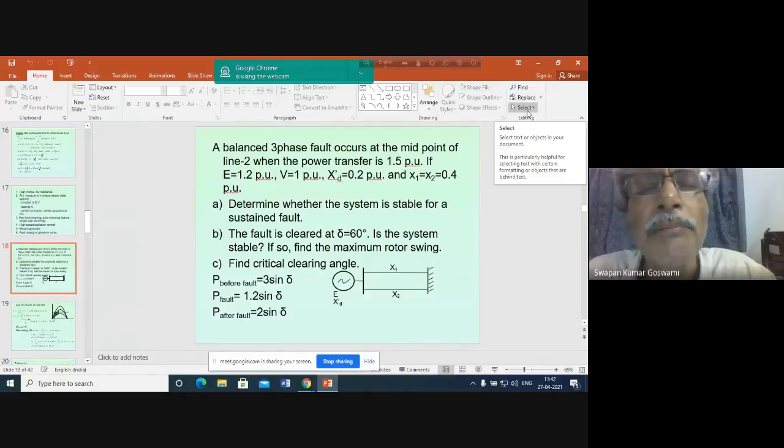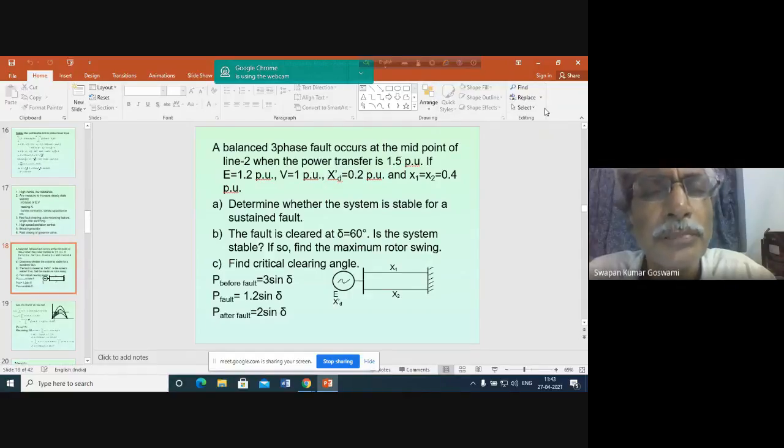Obviously, the transient reactance will be somewhat larger than the subtransient reactance. Why? Because the opposition from the damper winding flux has been withdrawn, but still the steady state condition has not been achieved. So before the steady state condition is achieved, and after the damper winding current is made zero, it is a transient period.